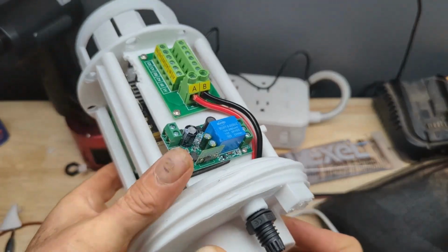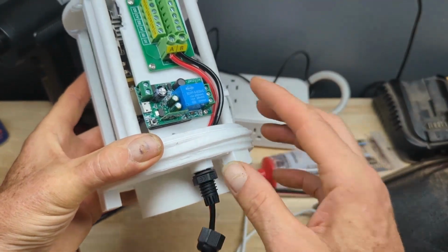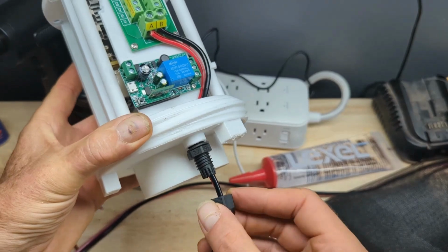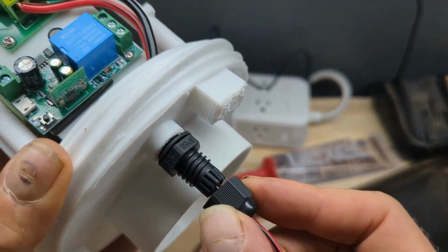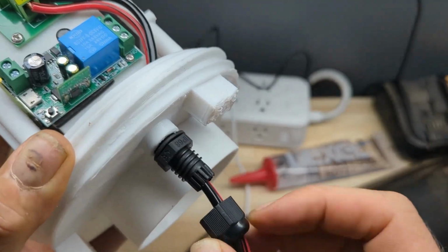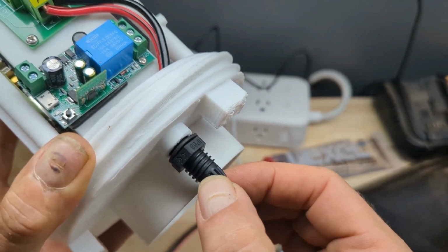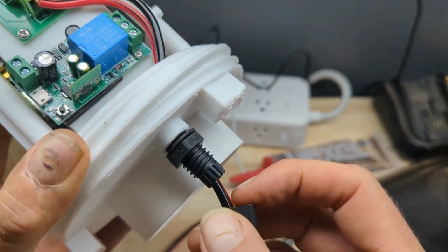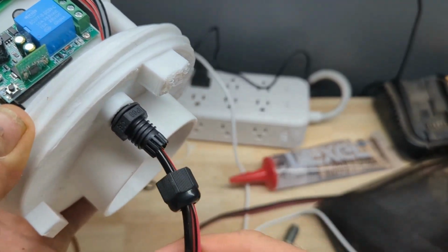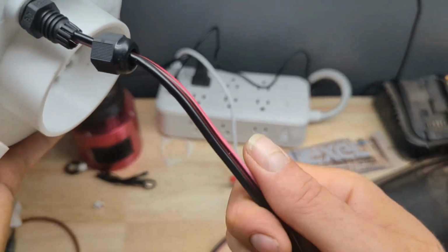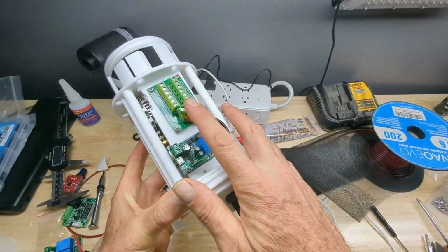And then one other thing I want to point out is I failed to do this. This cable gland, once you get the power in there, you do want to make sure that you secure it. See these little fingers on here? As you put this nut on here and twist that down, it's tapered inside, and it will start squeezing these fingers down really tight to where this wire would have a very, very difficult time pulling out, because you don't want to snag this wire and have it yanked out of your power block.